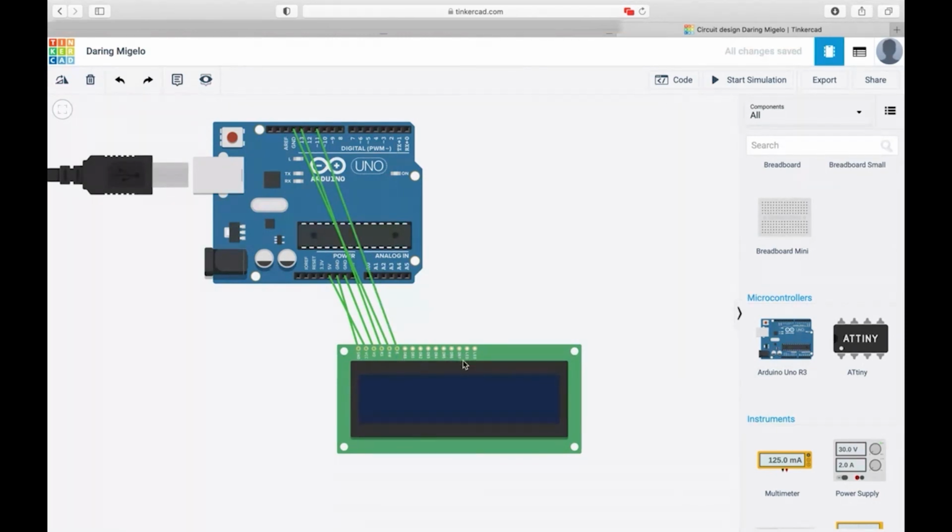Next, if you look on this LCD, you have DB0 to DB7. There are 8 bits, the 8-bit mode on the LCD. But when we have to display text, it is used in 4-bit mode. That means out of these 8, only 4 are used. Like this is DB7. You choose any 4 pins to display the text. So you connect it like this.